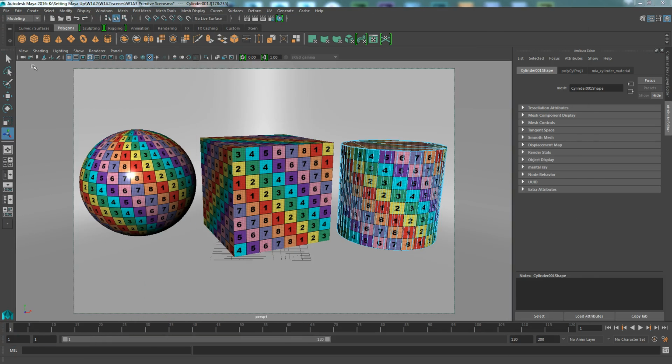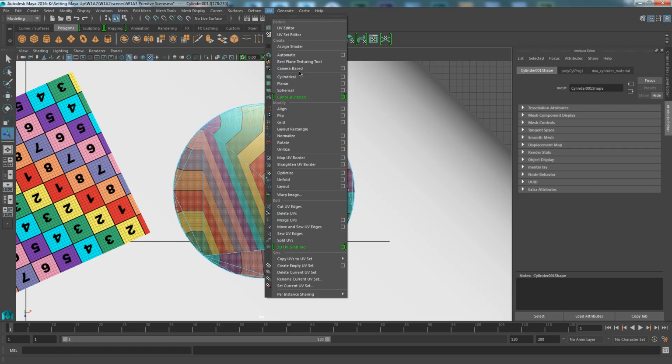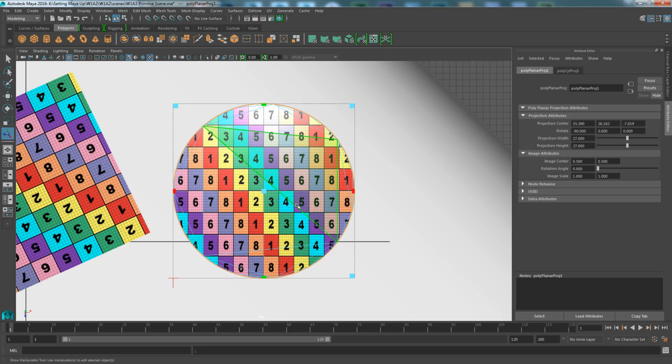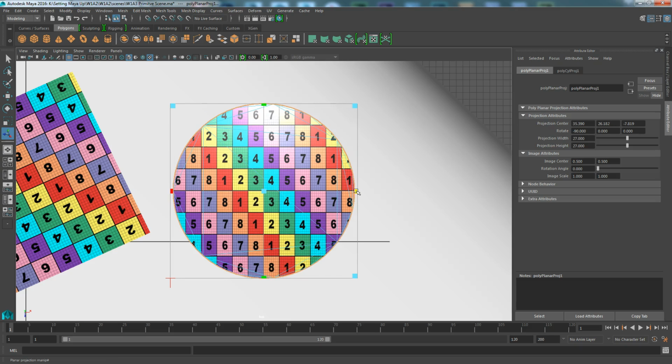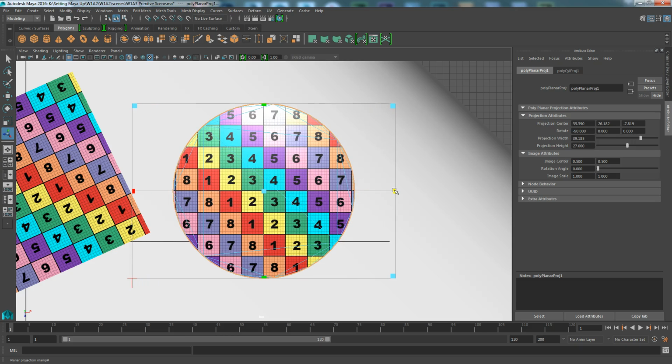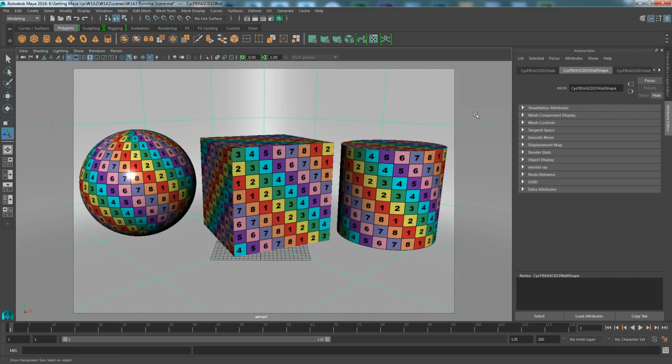and let's go in here and go to the top. So see that? We want to go UV, and now we're going to do planar. Okay. And then that'll put a mapping coordinate planar from the top. Okay. Now you'll see that that's a little bit stretched. Two ways you do it, that you've got this gizmo in here right now. So you can actually grab this corner and kind of drag that out. So they're squares. That looks pretty good. And so now we're ready to go back to our perspective, and there the mapping coordinates done on this.